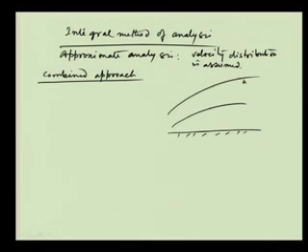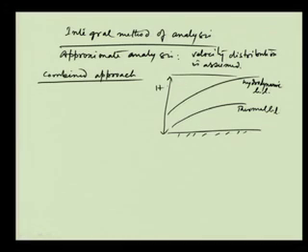This one I will say is hydrodynamic, and this one I am saying is thermal. The thermal boundary layer is lower than the hydrodynamic boundary layer, and above this the total height is h. At any point this is delta, and at any point this is delta t, and h is greater than delta, which is greater than delta t, the thermal boundary layer thickness, and this is the wall temperature T w.